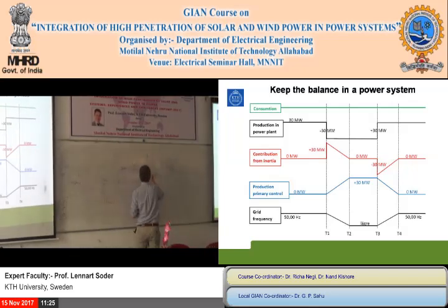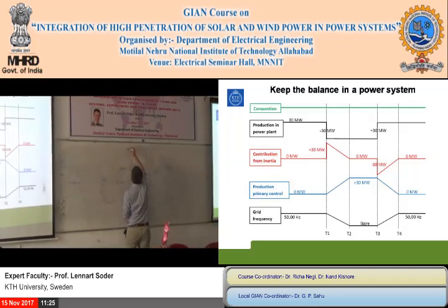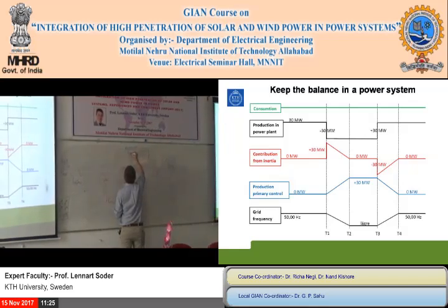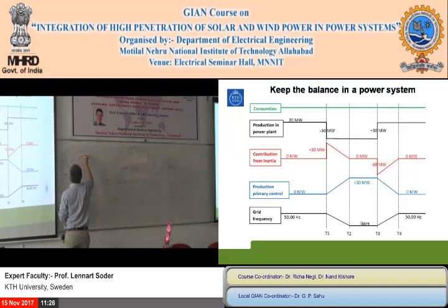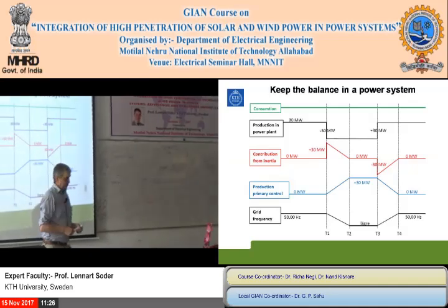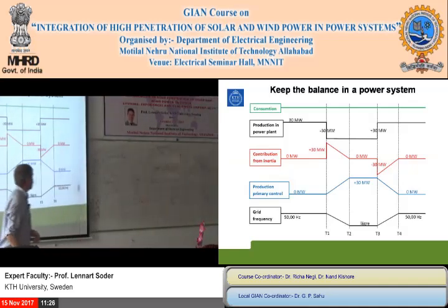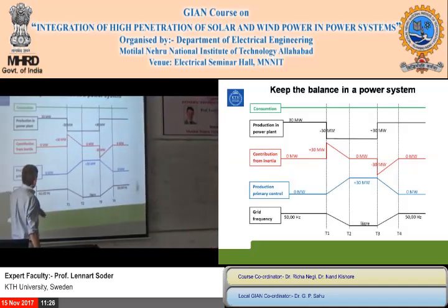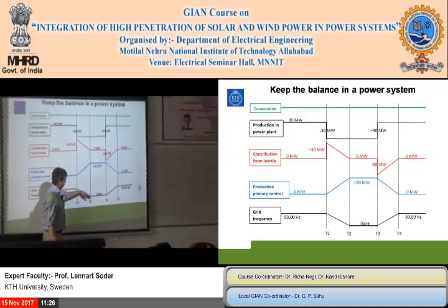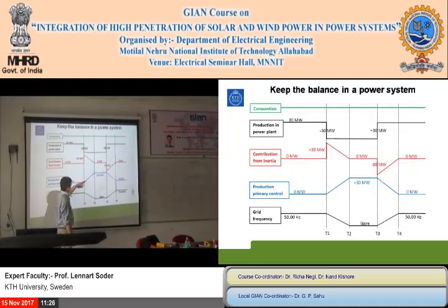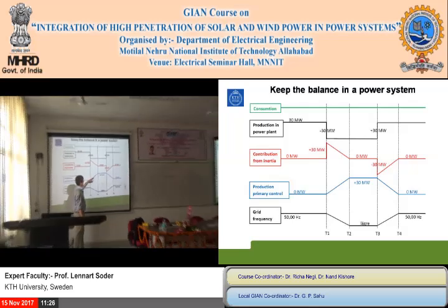that you here measure frequency and control P mechanical. And that is your primary control. And that is what is happening here: the grid frequency decreases, and when the grid frequency decreases, then the production is increasing.